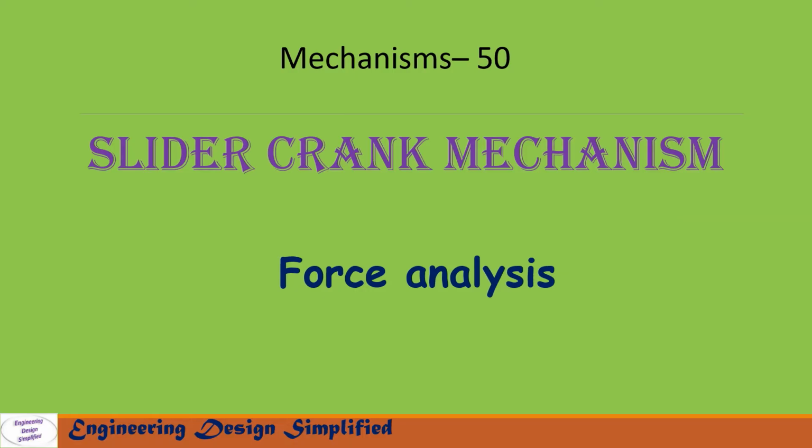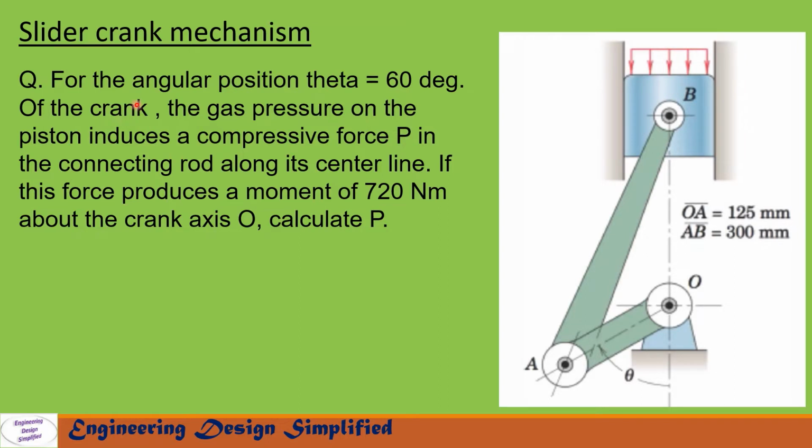In this video, I am going to discuss slider crank mechanism static force analysis. In this problem, for the angular position theta equal to 60 degrees of the crank, the gas pressure on the piston induces a compressive force P in the connecting rod along its center line. If this force produces a moment of 720 Newton meter about the crank axis O, calculate P.